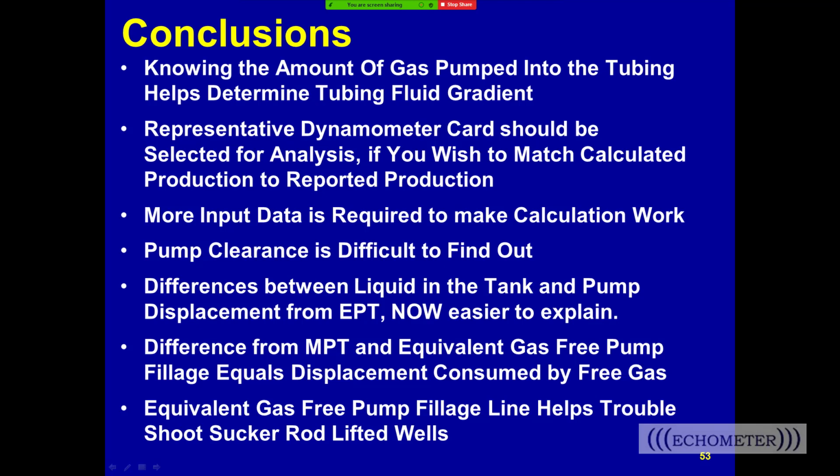So those are the two reasons for it to be wavy, but it could be wavy if the fluids are surging away from the pump, which I think is unlikely. So in most cases, the discharge pressure and intake pressure are constant. And so the idea of a flat line on the upstroke and downstroke of the pump card means that at the pump intake, there's no change in load acting across the plunger.